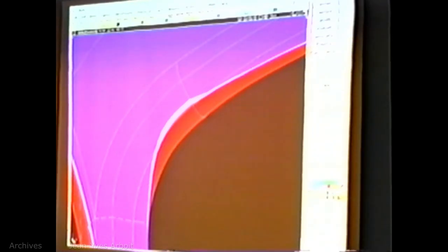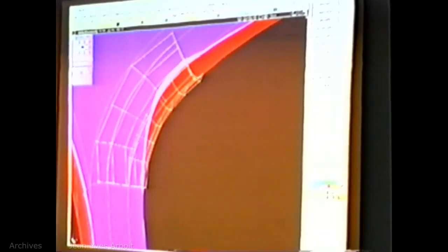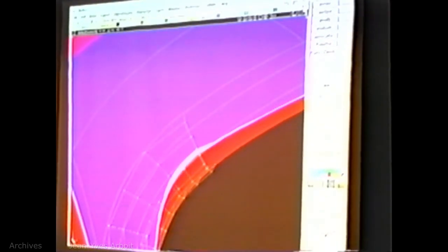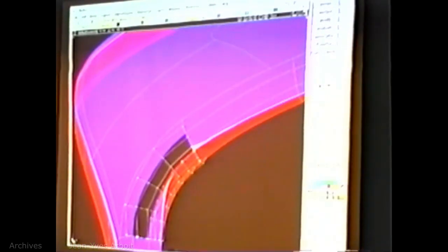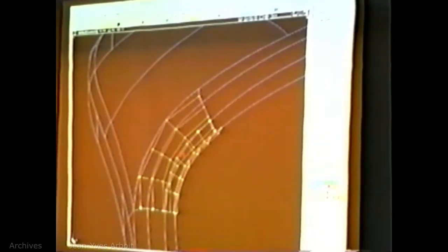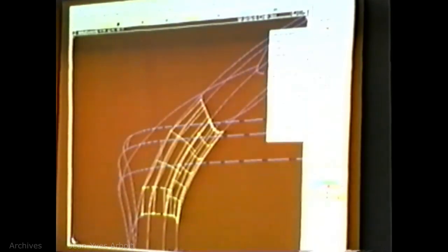But at the very least, this is a nice feature: if I put transparency on, and I've got the draft analysis on, and then I pick some of these surfaces and turn on the controls, you'll see that it updates very quickly. I'm going to modify CVs now to change where that draft line is. And actually the draft line itself, so if I turn this off, whoops, turn them all off, and pick these surfaces, I could pick more, but I'm going to use the evaluation tool.